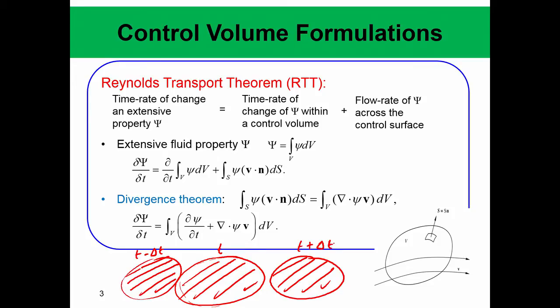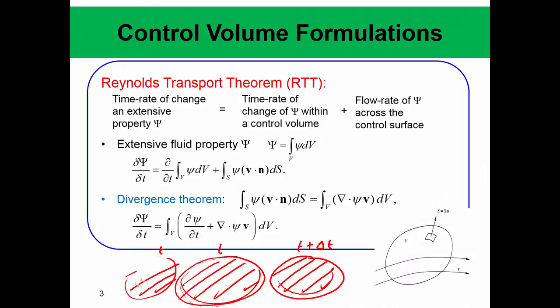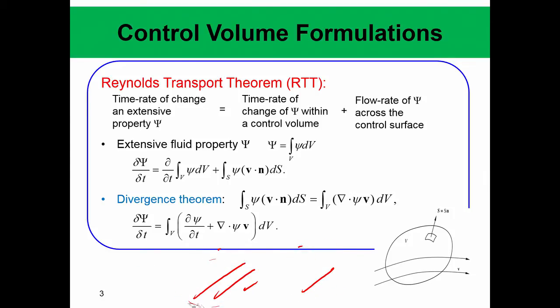Now, what I want to say is that the laws of physics, like Newton's law or the mass conservation that you know, are for this packet of fluid which is moving. The mass of it is not changing, the momentum, if there is no external force, is not changing, and the energy, if there is no external supply or loss of energy, is also not changing. But that is not what we are interested in. We are interested in applying this law inside a control volume.